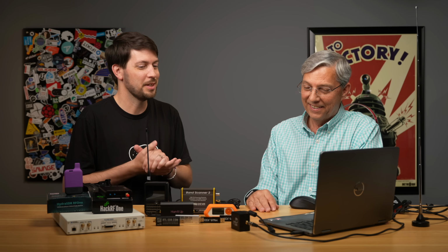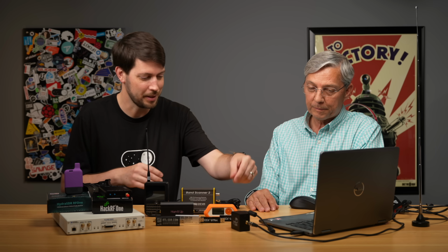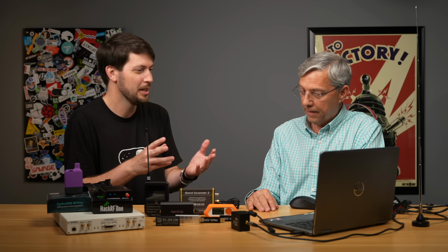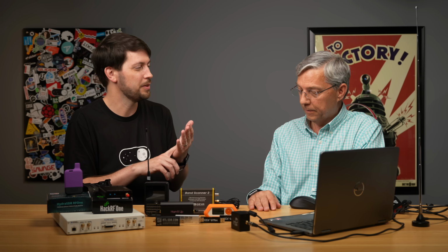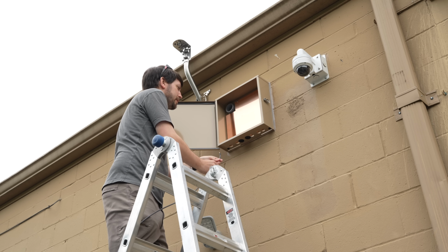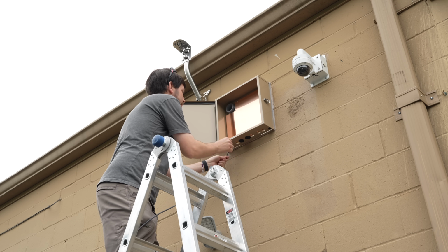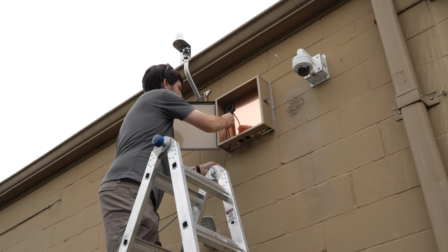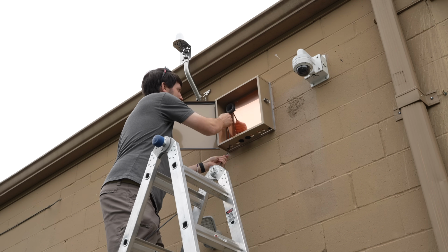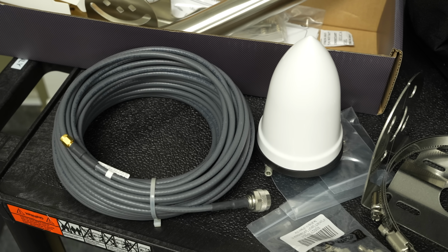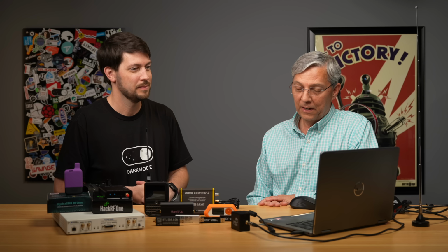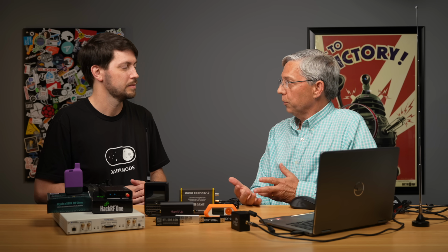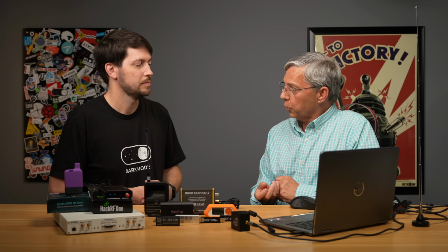Well, I noticed the other thing too is even the coax cable, all these cables are slightly different. They're different thicknesses, they have different shielding. But you were talking about the RG58 or the H11, whatever the cable is that I'm using for the GPS antenna. You said it does make a difference. Yes, cable makes a difference for many reasons. It's like a whole science in itself. And you never go bad buying really good cable. That's just a fact. And the other thing I was going to tell you, we use chokes to keep RF out for sure, off of control lines and things that are slower than the RF.